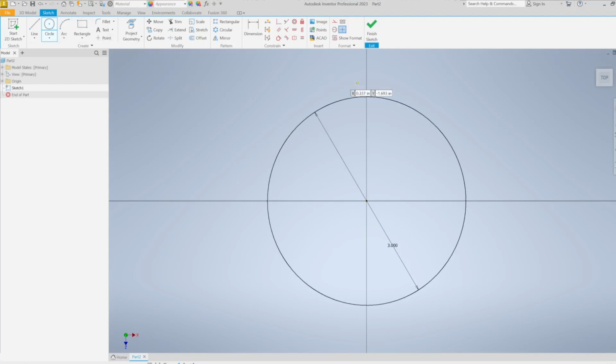And I'm going to make a rectangle, or part of a rectangle. I'm going to use my line tool here to make this rectangle up here, just like that. Now I want to make sure that my lines are touching, right? So I'm going to pick that endpoint in my circle, that endpoint in my circle. I want my midpoint to be directly over top of that, so now it's spaced out properly. And that dimension is going to be 1 inch. So click there, hit 1 inch. Okay, so now that kind of grew as it's supposed to.